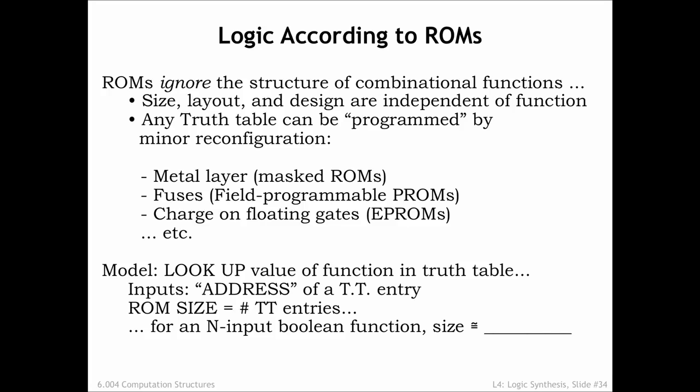A separate physical or electrical programming operation determines which switches are actually controlled by the decoder lines. The other switches are configured to be in the permanently off state. If the ROM has n inputs and m outputs, then the switch matrix will have 2 to the n rows and m output columns, corresponding exactly to the size of the truth table.